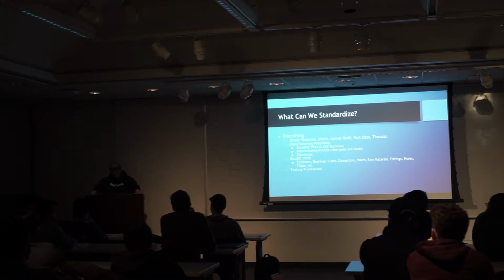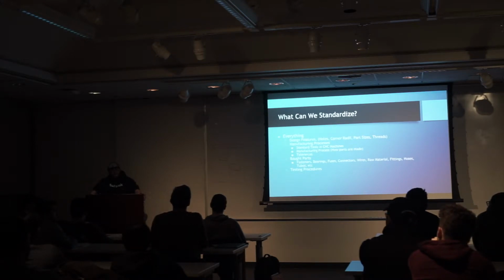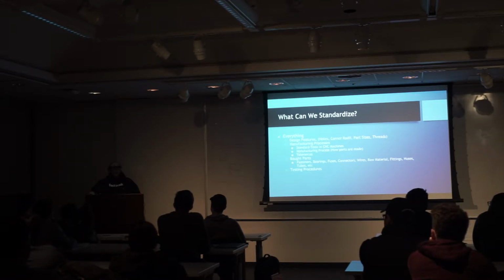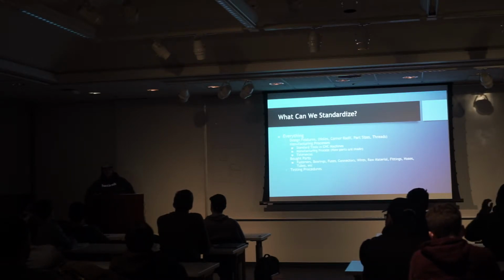Yep. It seems like for different parts, you have different procedures, different ways to test them. How would you go about standardizing two completely different tests? Yeah, so each part is going to be tested somewhat differently, right? But you guys haven't done as much testing, right? If you're going to put something on a vibration table, you want it mounted roughly in the same way. You want the temperature to be the same. You want to make as many of the variables the same as possible. And it's not as simple as just saying, yeah, we're going to test them all the same.